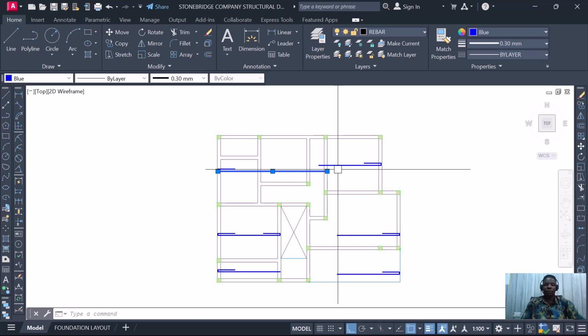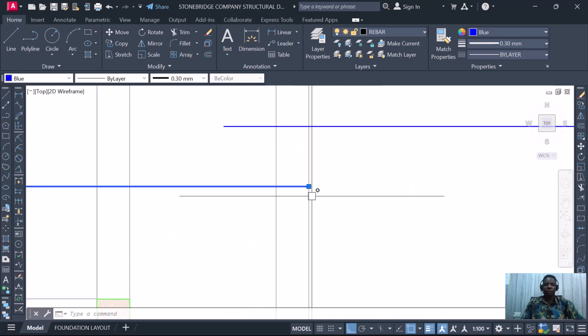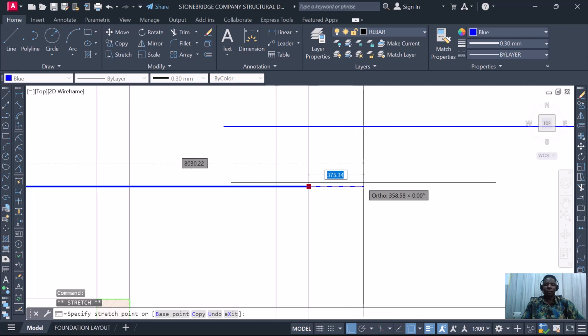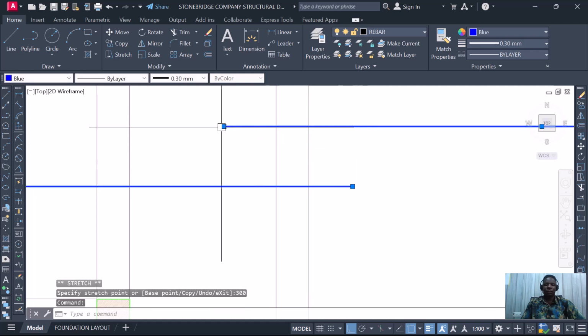If we are doing our flat slab detailing, we also tell you the process and what you are supposed to do in a flat slab detailing. But since this is a solid slab detailing, we have to consider this to be a solid slab detailing. We have a solid slab, a ribbed slab, waffle slab, flat slab, different types of slab. In all of them, they have different considerations for how to lap them. You don't just say, because you have a beam reinforcement on site, you don't want off cut, I just want to do it. Sometimes you have to consider off cut, and sometimes you have to look at what is more critical, because stability is your priority. A good design should be your priority.